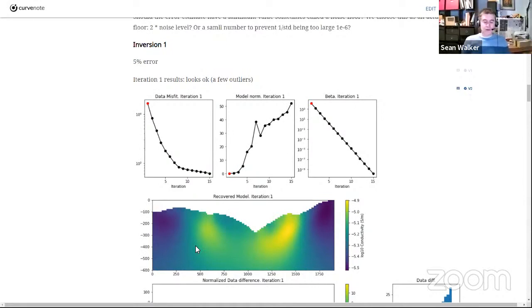Yeah, and that's a whole other thing. Getting into 2D and 3D, with DC resistivity surveys in particular, you're collecting 3D data because the source currents can flow everywhere, and they do, but you're really just putting everything down a line. So you assume the world's 2D, but you could throw this data into a 3D inversion if you wanted to. And even with multiple lines, generally you're not reading across the lines.